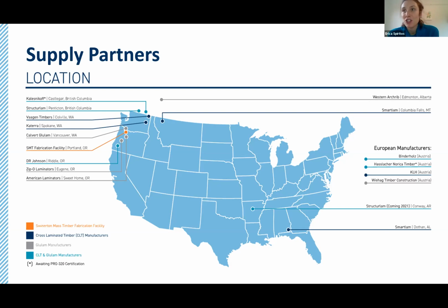So that 3-ply panel generally spans 10 to 12 feet, depending on the live loading criteria and requirements in the building. In this specific building, we've got 10-foot spacing between glulam frames, so that CLT panel is spanning 10 feet. And we found that that was really amenable to a number of different supply options and reduces waste pretty much with many of those suppliers or manufacturing partners. So those are some of the initial considerations.